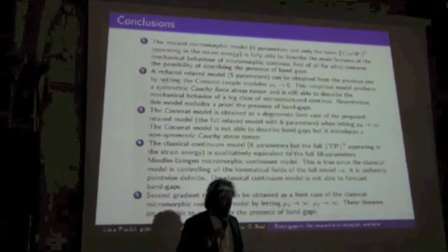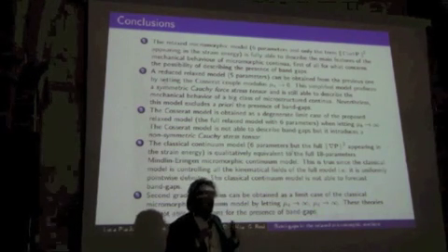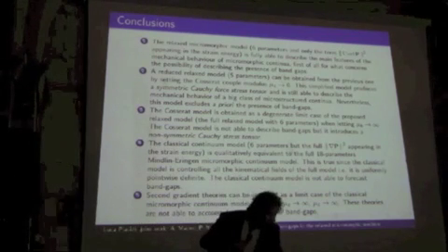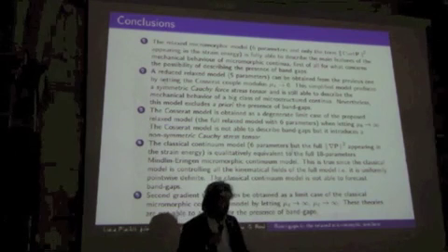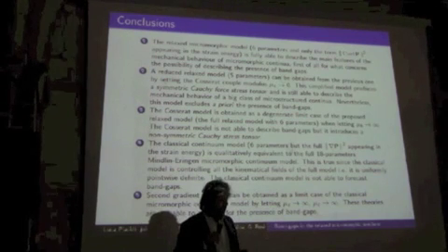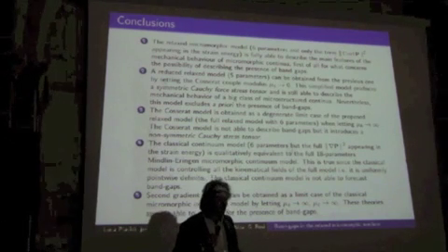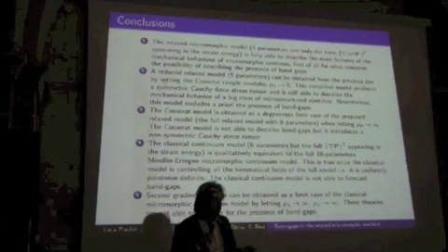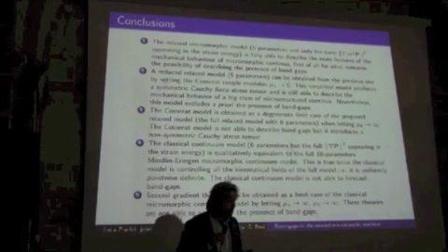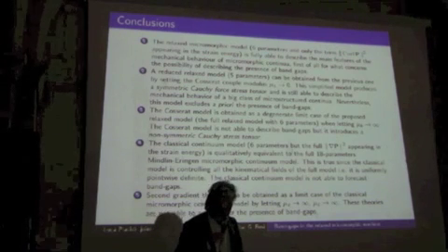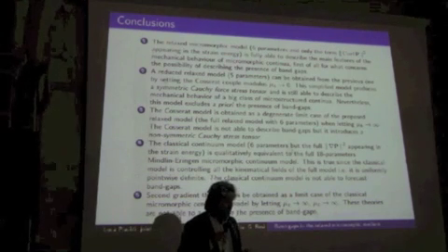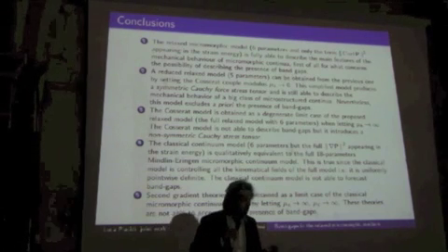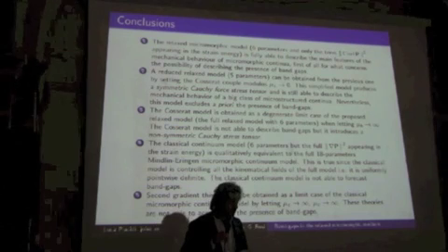The relaxed micromorphic model has 6 parameters, and only the square of the curl appears in the strain energy, and it is fully able to describe the main features of the mechanical behavior of micromorphic continua. First of all, for what concerns the possibility of describing the presence of band gaps.